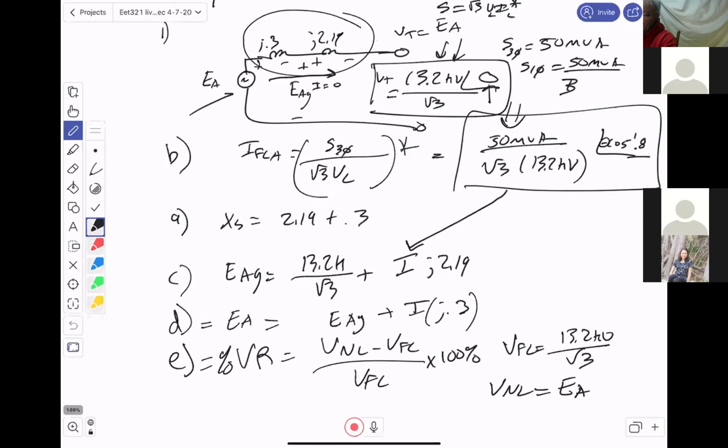And essentially the reason is, remember what determines what my EA is. EA is equal to K times phi times omega. So that's when we had those curves. This is our field current, and we had something that does this. That is the EA. So it's interesting, but the actual armature voltage that you have is really just determined by my field current. So when you talk about operation of the grid, you can just control the amount of field current, and that'll either increase or decrease the excitation to the point where you can change your power factor on your generating unit. And it's all based on just controlling the magnitude of that voltage.